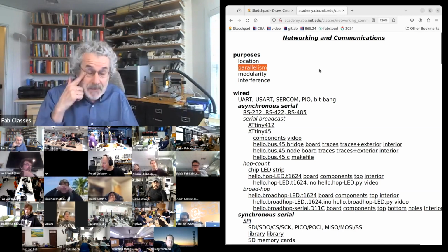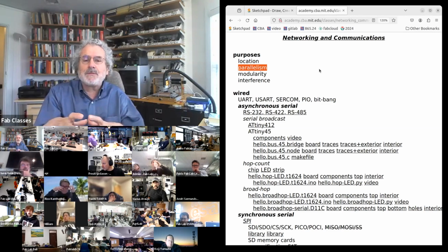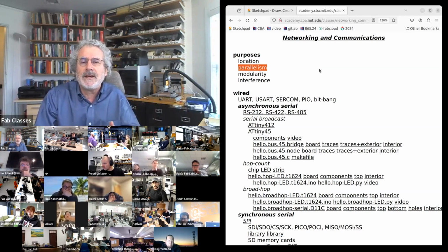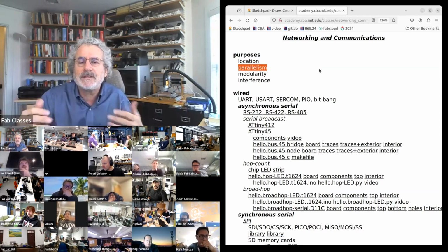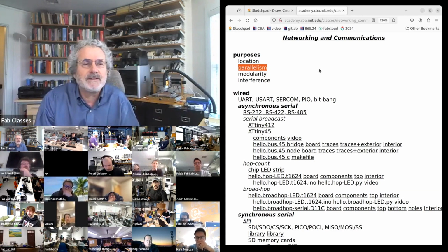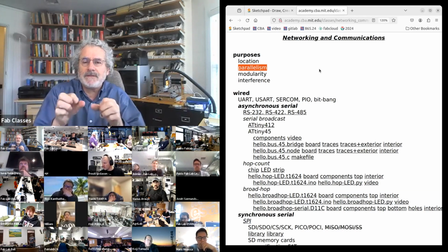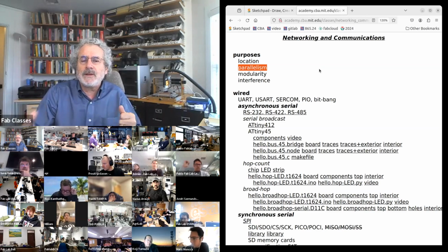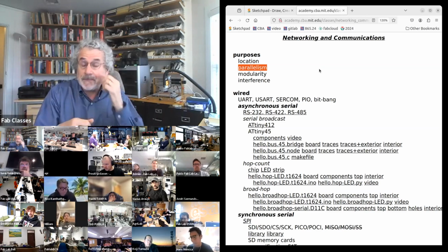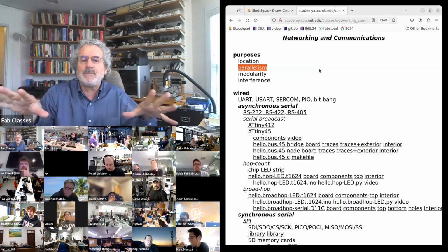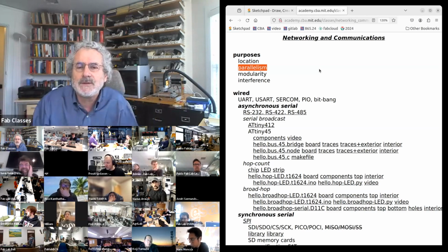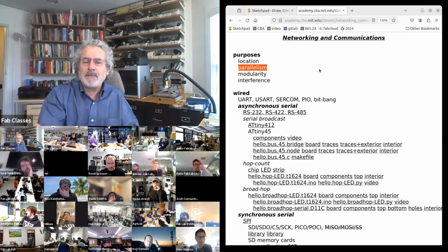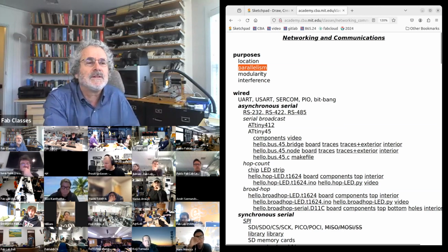So one is parallelism. As your project gets more complex and the processor needs to do more things, you can move up to a bigger processor with a multitasking operating system, or you can have separate processors each doing one task. So for the environmental sensor, each sensor can have one processor, and then rather than having to read them centrally, each can have associated processing. So you can scale a system by making multiple processors separately instead of multiple cores in one processor.